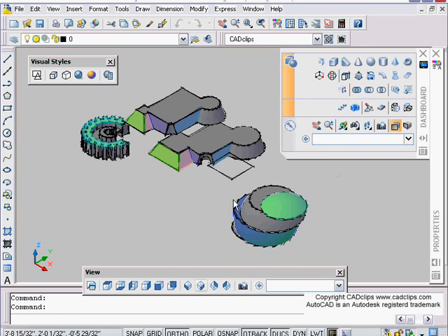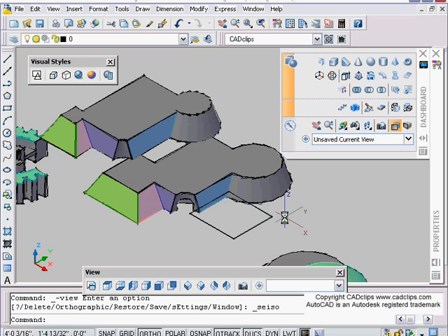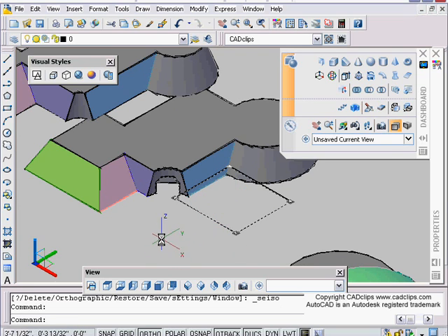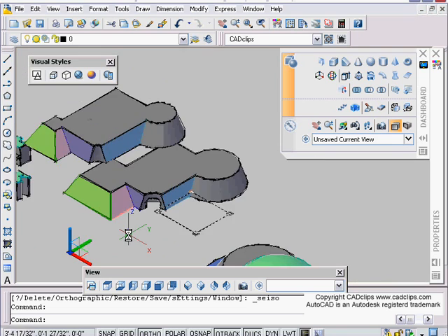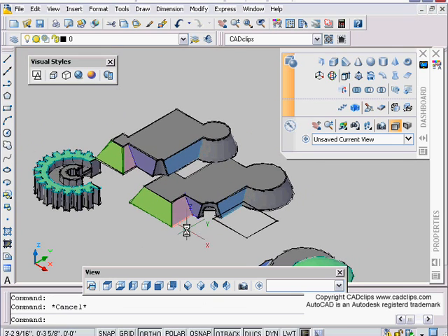So I have to admit, slicing by object can be quite challenging at times. The main thing is to draw the object on one plane, switch to a perpendicular view, and move that plane up and down. And when you do the slice, I recommend resetting your UCS to the plane that the slicing plane was drawn on. So a couple of little extra tips there. And once again, as a prerequisite, have a look at our previous 3D videos for AutoCAD 2006.